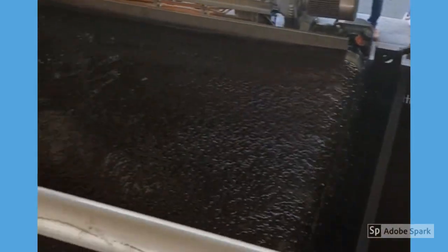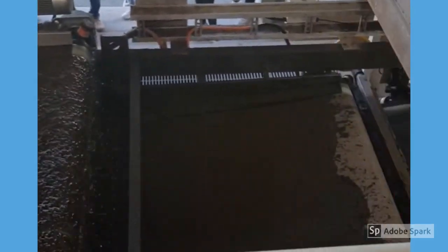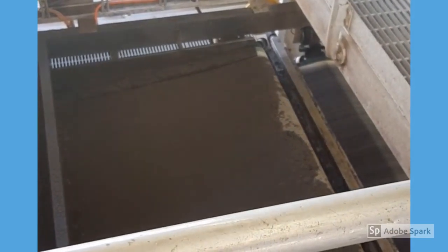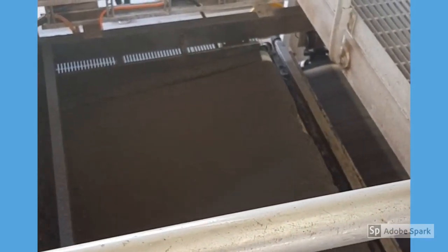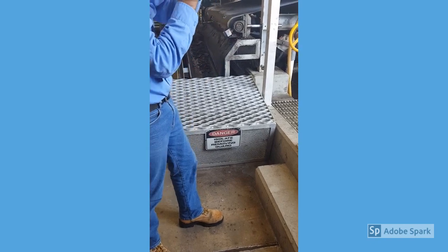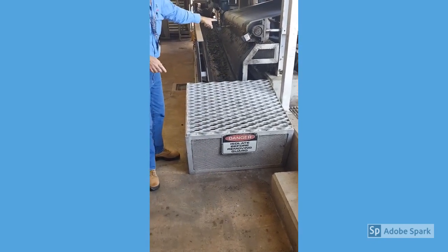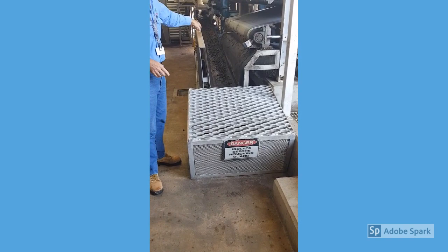As can be seen here, the dewatering process separates water and sludge and transfers the sludge further into the plant for compressing. The filtrate from this process is returned back to the head of the plant for further treatment, whereas the solids are collected into large bins as can be seen in this video. This solid biowaste is removed from the site and sold to the agricultural sector as an effective fertilizer for animal feed crops. This dewatering plant has a capacity of 600 kilolitres per day and may produce 15 tonnes of biosolids every day.